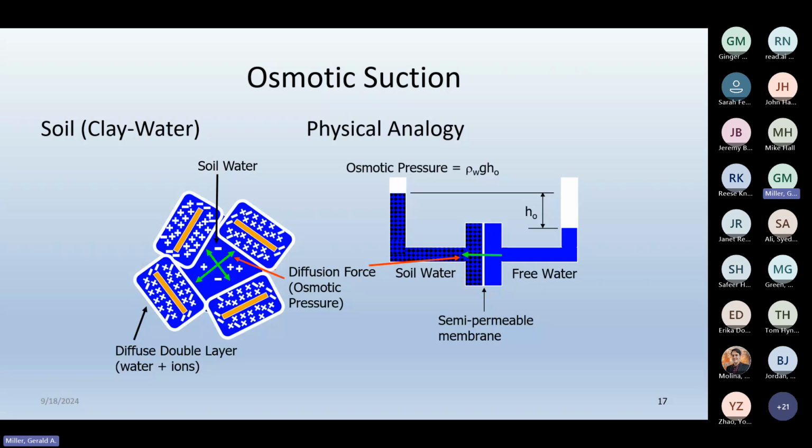You can have diffusive forces acting within this structure that can affect the behavior, more so in clays than in sands. But basically that picture on the right sort of illustrates what osmotic suction might look like.